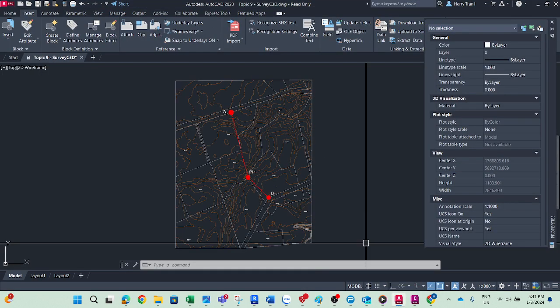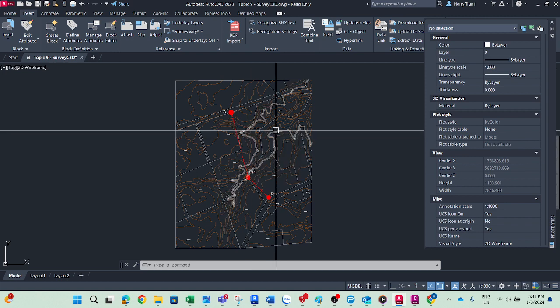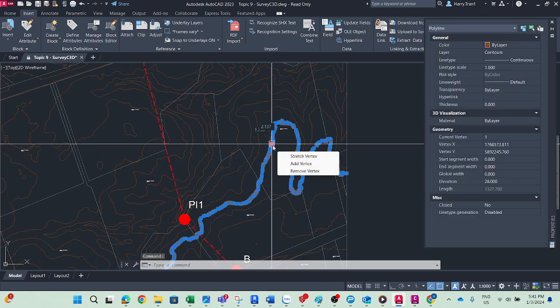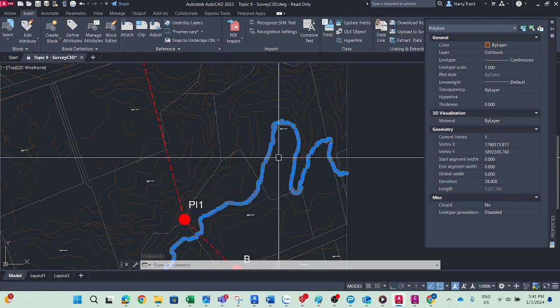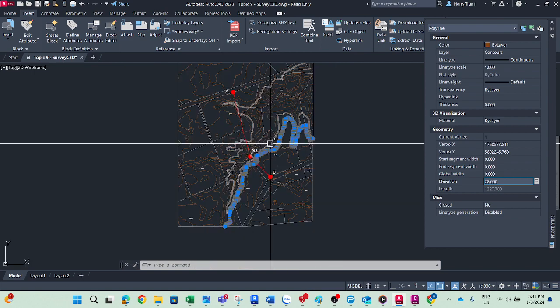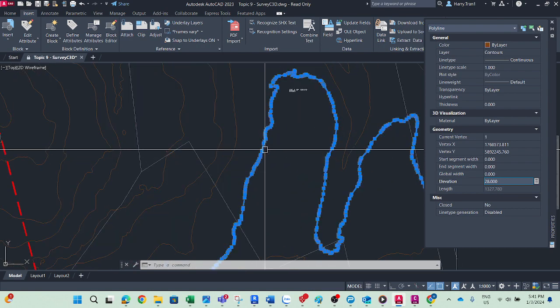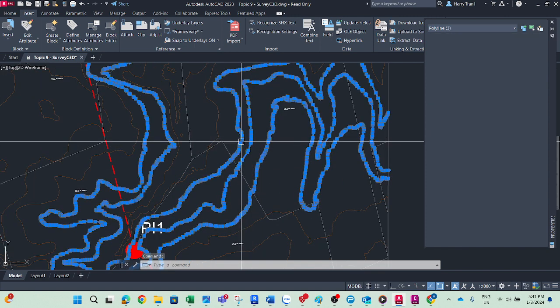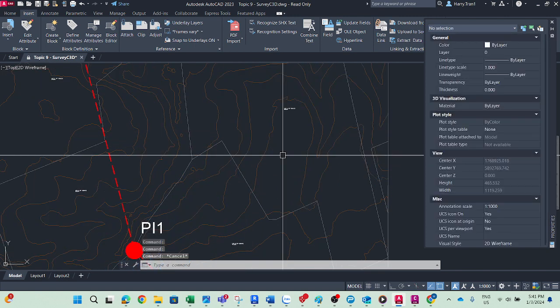In AutoCAD we open the survey file with the contours. So you see a contour on the screen with the elevations in the properties dialog box. To copy these contours, we need to select all of the contours. You can do this manually, or another way is to use the filter command.